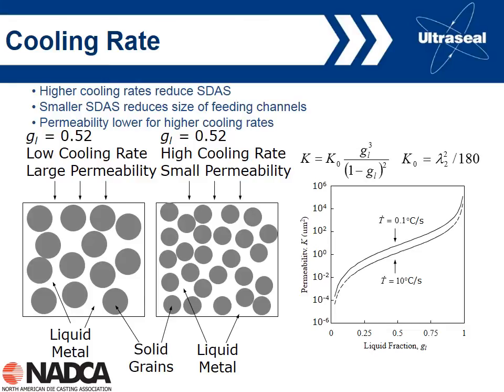but what we're showing is the effective cooling rate. We are representing the solid that forms as these gray discs, or gray spheres. On the left, we've got a low cooling rate, so we've got coarse grains formed here, and the liquid is just the white area. On the right, we've got the same solid fraction, but a higher cooling rate.